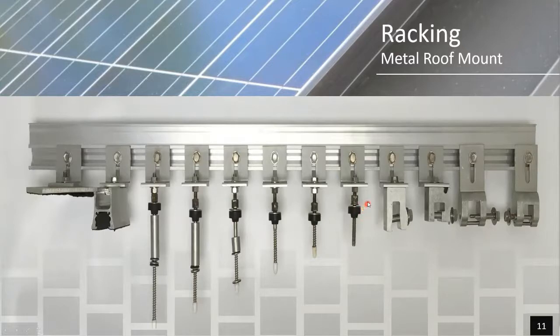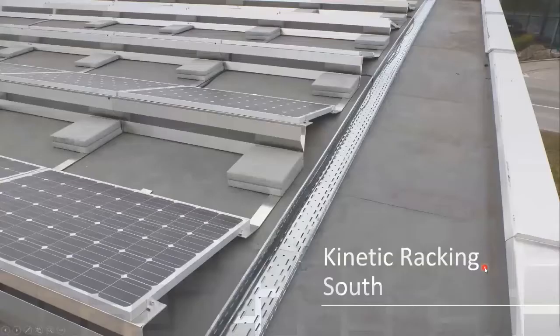So now to find the truss or the rafter, it's a little more difficult because I've got metal roof strapping, asphalt, then I get into the sheathing of the roof, and then finally into the rafter or truss. A little more difficult. These have neoprene gaskets, so you'll typically see these mounted directly into the strapping, those flat plates, or if you can, the standing seam S5.